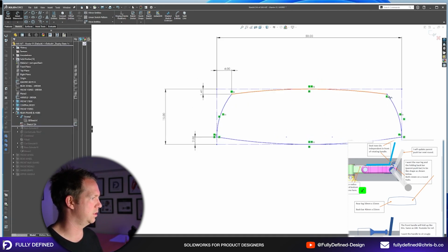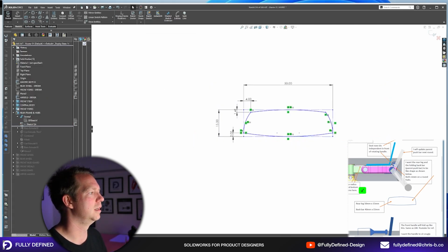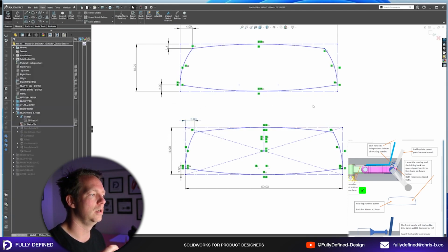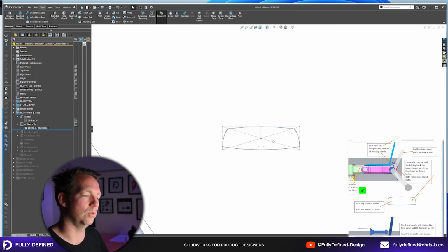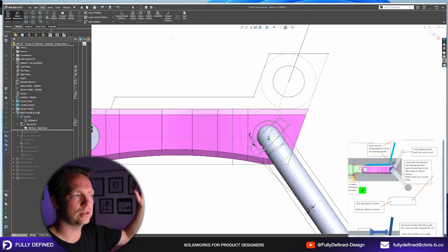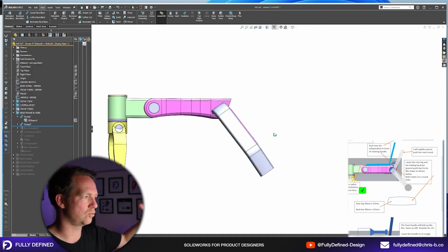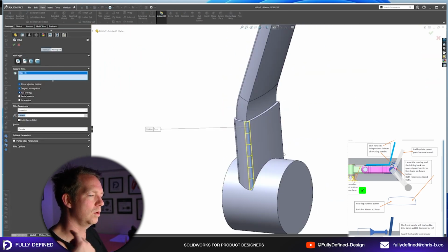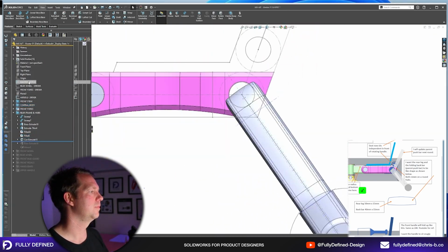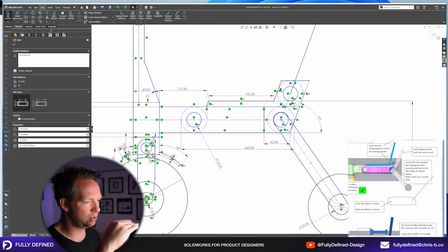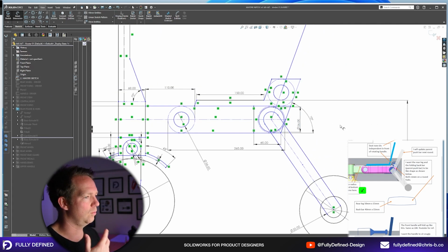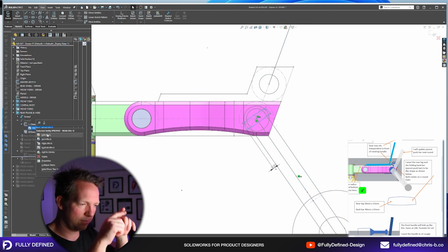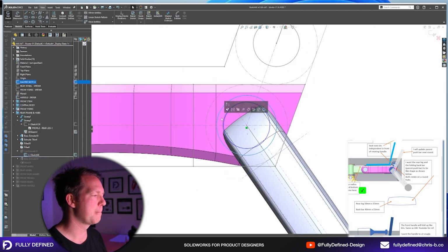So let's say you've just been doing some direct modeling and you've added some new features, and some of those features are very key to the entire model. You want to get them back in your master sketch, but you can't because those references are actually down the bottom of your feature tree. What you can do using Sketch is start a new sketch where you are in the tree, convert whatever edges, geometry, etc. you need. So you've got them in that sketch, it's a copy.